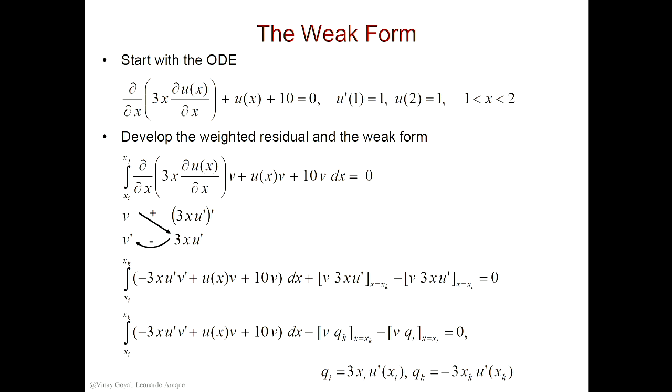I call these Q's, okay, because here what I wanted to point out is that what is not V is Q. What is not V, I'm at a Q. And what I wanted to point out, this V tells you what is an essential boundary condition, what is not, natural boundary condition. Here V tells me that if I make this V into U, whatever is specified on U is an essential boundary condition. Everything else here must be a natural boundary condition. So when I look here, I know that's essential, I know that's natural. Okay, very quickly I know that.